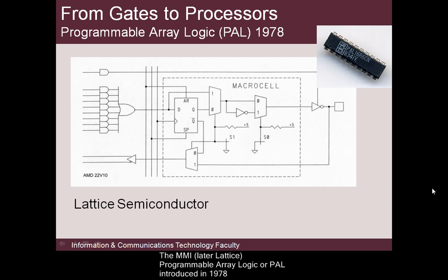At the same time, the device count and complexity of straightforward logic chips was also increasing. The programmable array logic, or PAL, introduced in 1978, followed the PLA pattern, but included a read-only memory chip rather than fuses for one-time programming by users. These devices developed rapidly in complexity, adding registers and output macrocells with various functions and added flexibility.